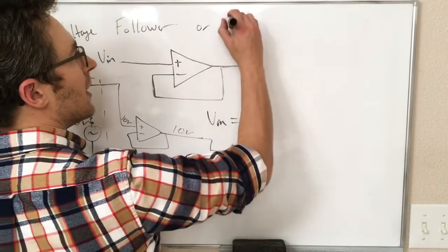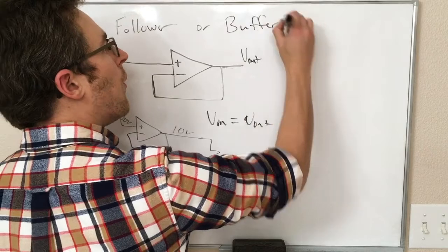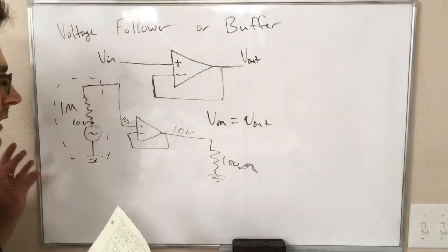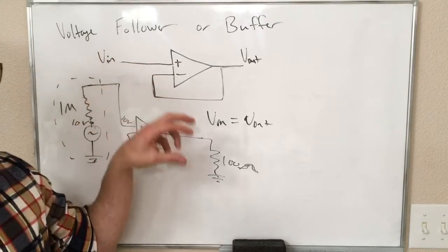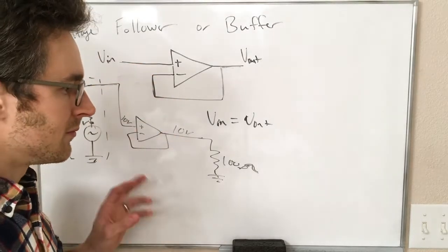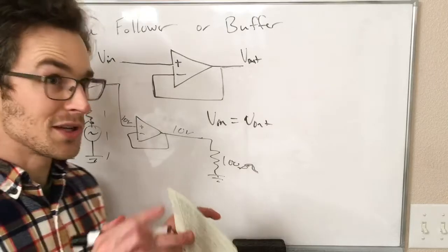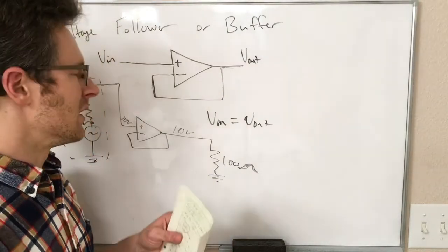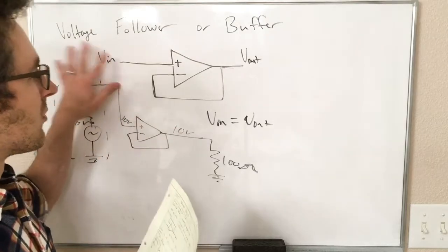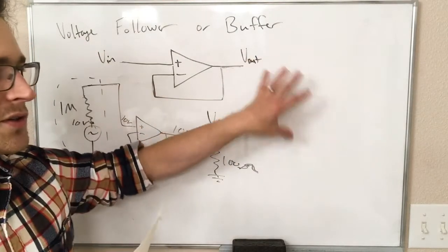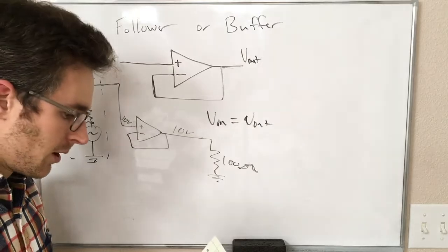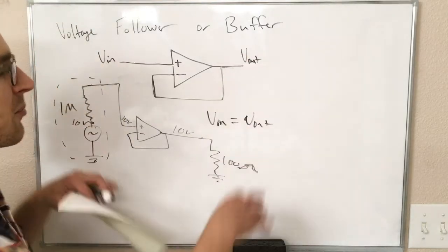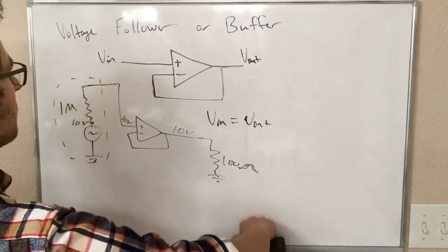This is also called a buffer. The idea there is that if you have some signal, you can send the signal into this buffer, and it holds and preserves it, not in the memory storage sort of way, but in the sense that whatever's over here is not going to be affected by whatever is drawing the current over here. That's what it means by buffer, and it acts to separate those two. All right, cool.